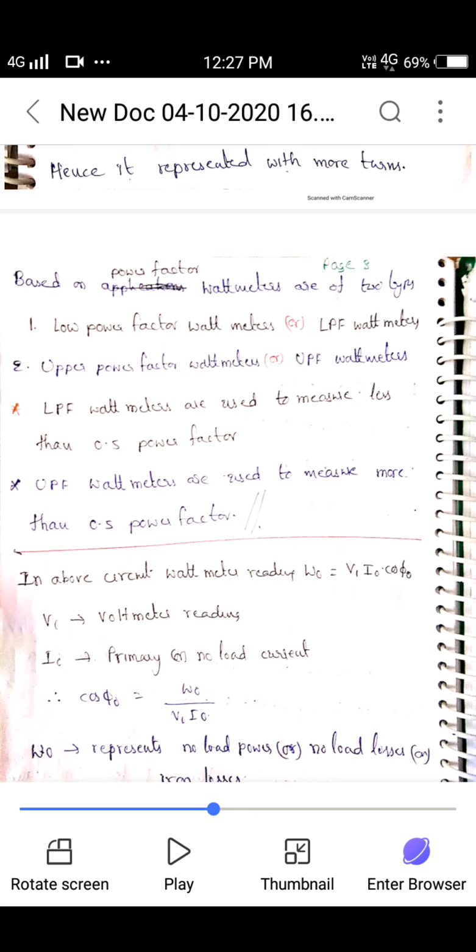Now which side do we have to conduct the test? That is the main point. We have to know the main reason. Any machine or any device gives best results at low rated value side. If you see a transformer, it always transfers constant apparent power. Now if you see voltage ratings, if the voltage is less on the low voltage side, that side current is high, because V1 by V2 is equal to I2 by I1. Now transformation ratio was already discussed.